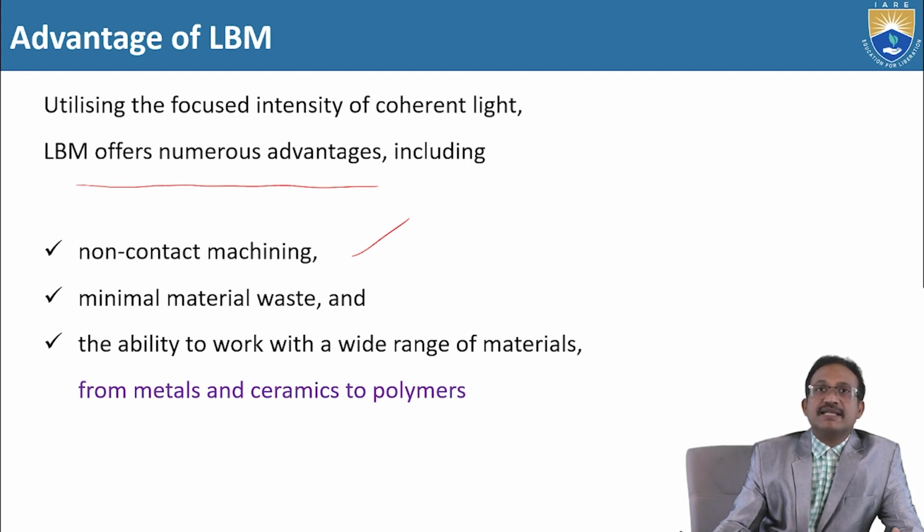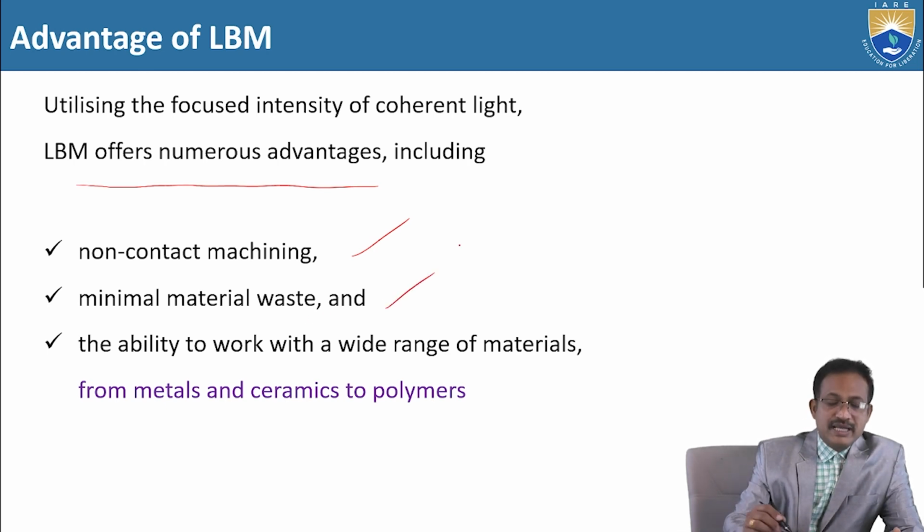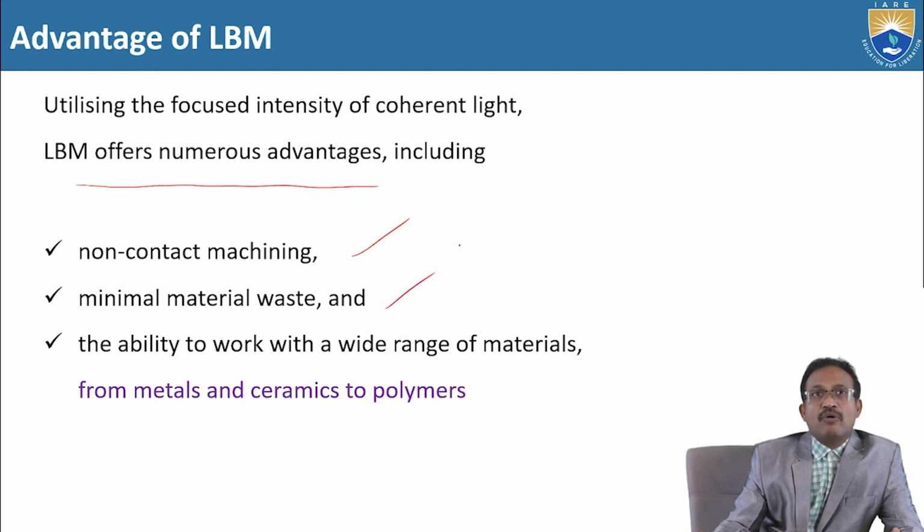This is the major advantage of laser beam machining. Minimal material waste, why? Because it points on a spot. That means a surgical material removal is taking place, and there will not be any large heat affected zone.